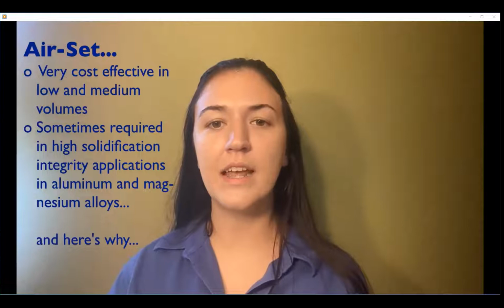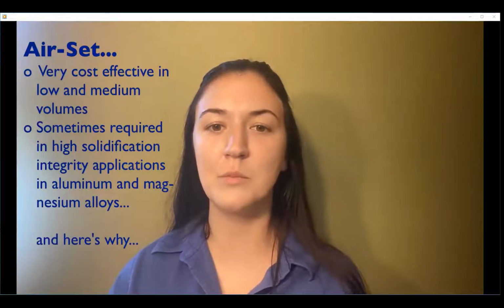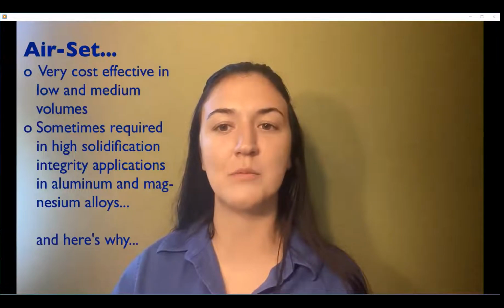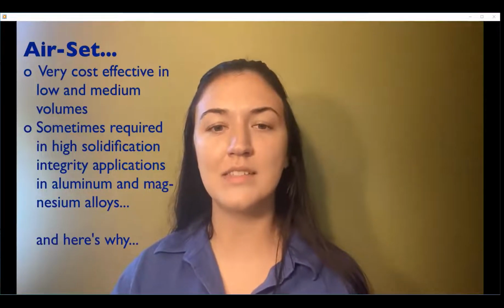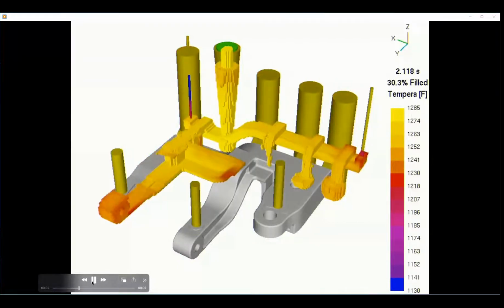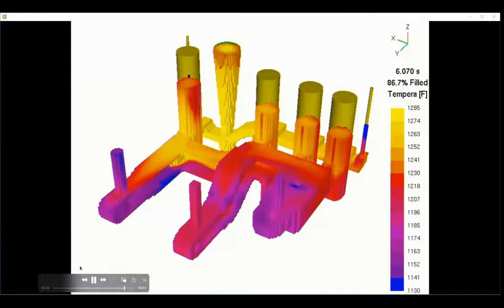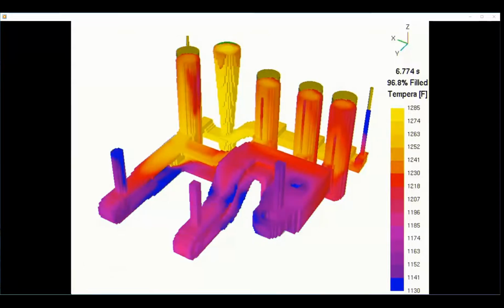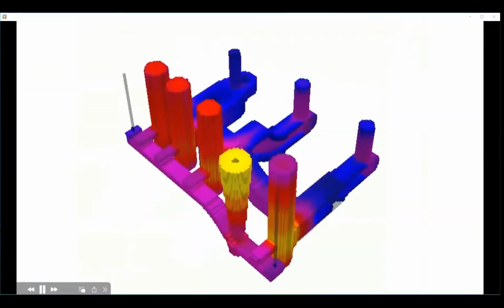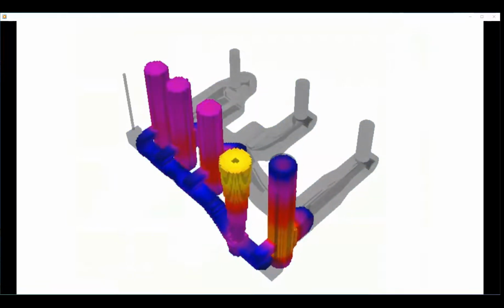In military and aerospace castings with higher designated mechanical properties in some regions of the casting design geometry, the airset sand process is required. The reason is the ability of the airset sand process to easily deploy temperature and mass gradients in the mold as the mold fills to achieve more rapid, more complete solidification where higher mechanical properties are required.